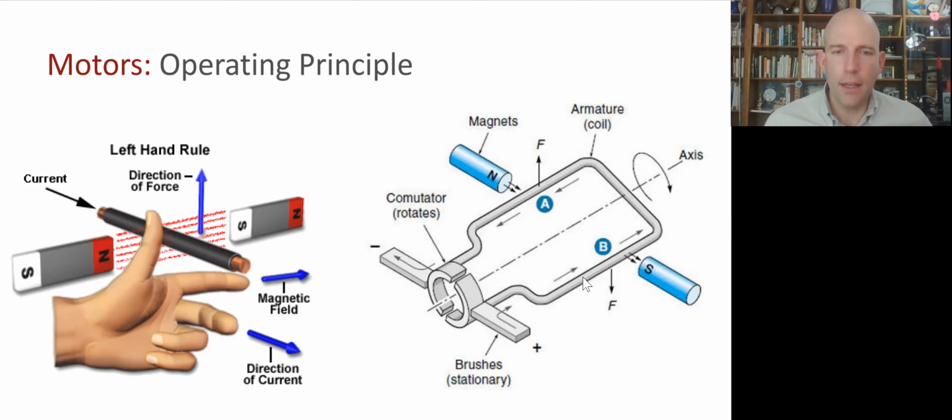And when the electrons flow through, we get a force down. And those same electrons will eventually go over here. They'll flow the opposite way, and it'll cause a force up in the same magnetic field. But they have opposite lever arms. And so they cause this thing to tend to spin. They produce a torque. And similarly, when you spin it, that moves the wires through that field and induces a voltage.